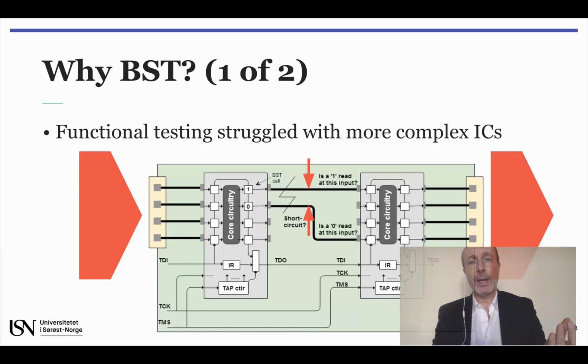If we want to find out whether there is a short circuit between these two nodes, for example, we must be able to drive opposite logic values to the corresponding output pins, but how can we find out what test values to drive at the input edge connector in order to set up these fault detecting conditions? And how can we propagate the error signal to an observable pin at the output edge connector?